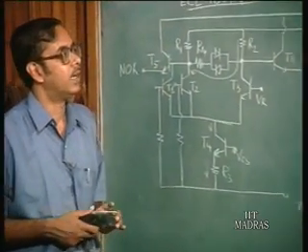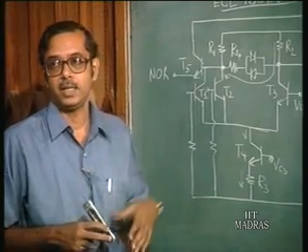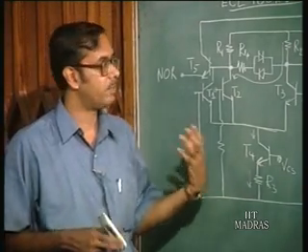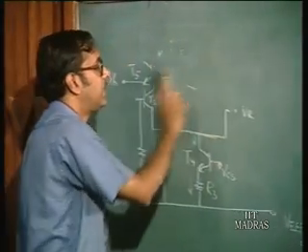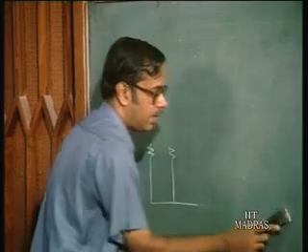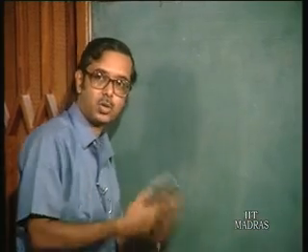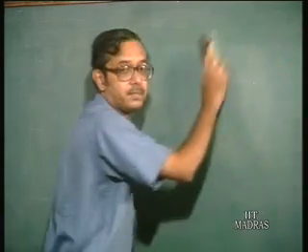One of the ways to reduce the power dissipation of an ECL gate is to improve the functionality of an ECL gate. By functionality we mean that if we can achieve a more complicated logic function using the same power dissipation.